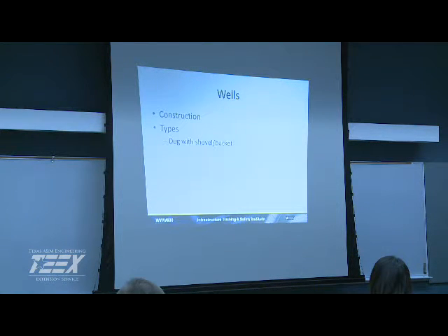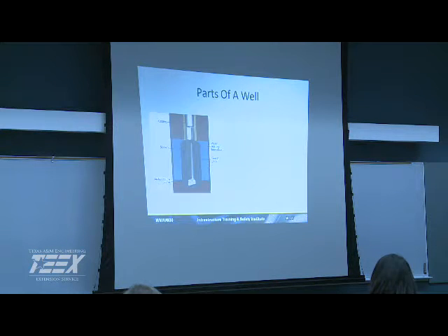When we're looking at our wells, how did we build it? How is it constructed? Back in the old days, talk about biblical times, out there shoveling, shoveling bucket. Then we get into where we can actually do it with an auger, depending on how deep it is. Not real practical unless it's a very shallow well. Driven, haven't really seen any driven points. That's old school, just hammer it down through whatever material is. And then of course the most common nowadays, the drill truck's going to come out and they're going to drill for us and put in nice casing and all of that.